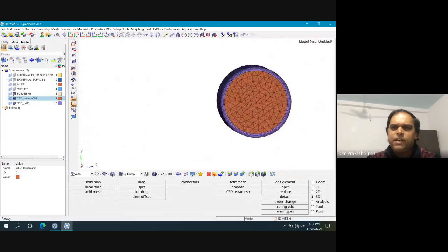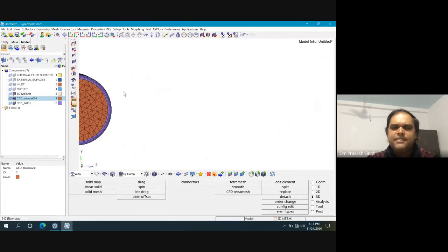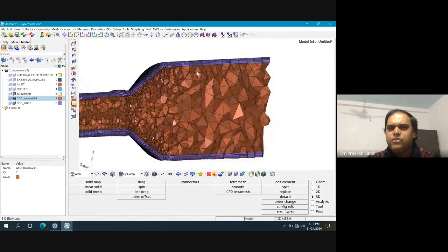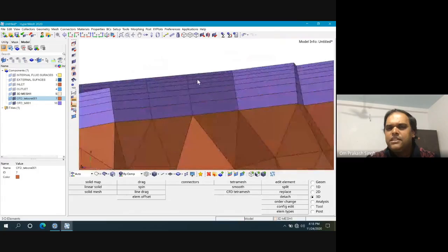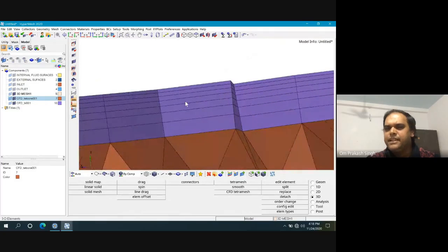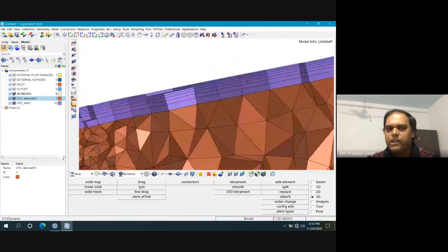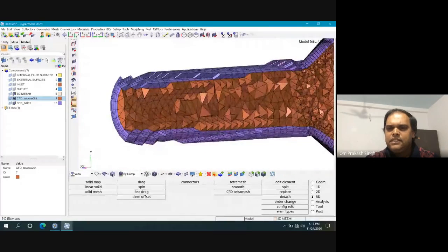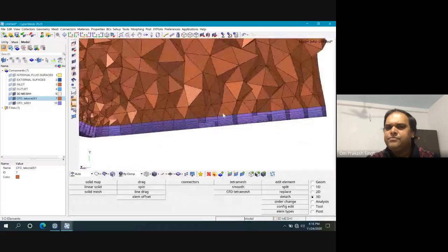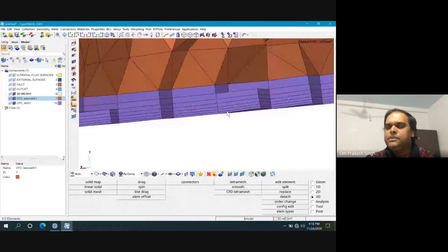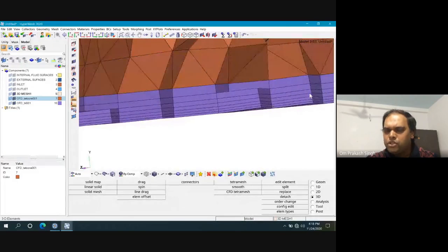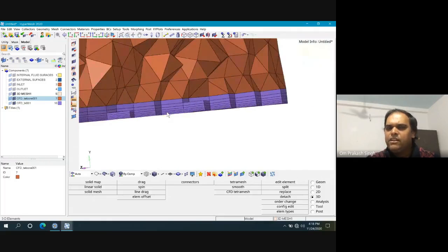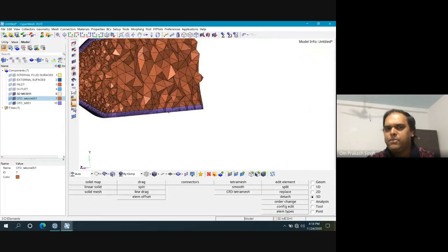And if you want to see the mesh, look here, you can see the layers. This is a layered mesh and it is also a little stretched. I will tell you later about the importance of mesh quality. So everywhere near the wall, a layer mesh has been created. Okay, since near the wall the flow is mostly along the wall, here the mesh can be a little bit stretched, and it will capture the stresses in a better way.